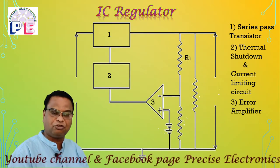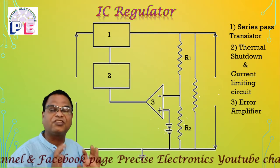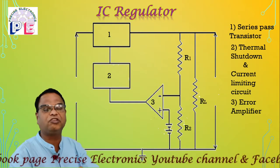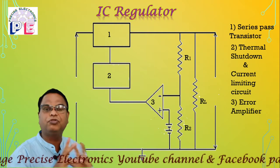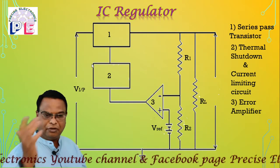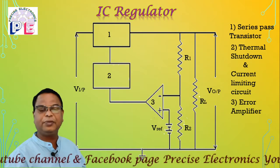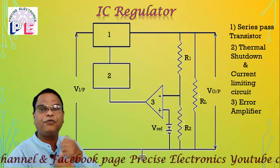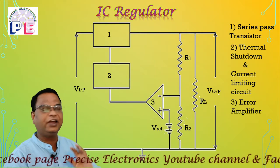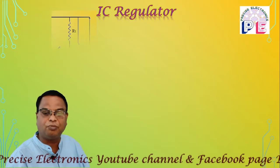And the fourth block is actually a potential divider network formed by the 2 resistors R1 and R2 of fixed resistance value. And a load resistor is there, across which the output potential will develop. So this is the block diagram of the 3-pin IC regulator. Friends, V input, that is the input voltage which is to be regulated, is applied to the input terminal, and the output potential, that is a fixed or constant DC potential, is developed across the output terminal. So friends, this is the block diagram of the 3-pin IC regulator. Now we are going to study the function of each block.